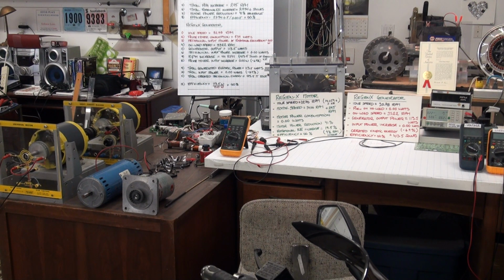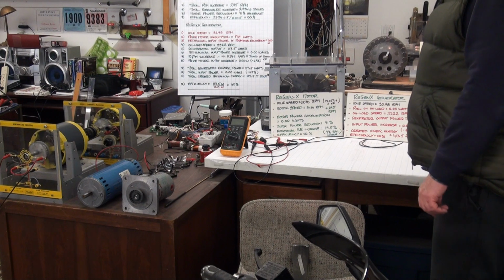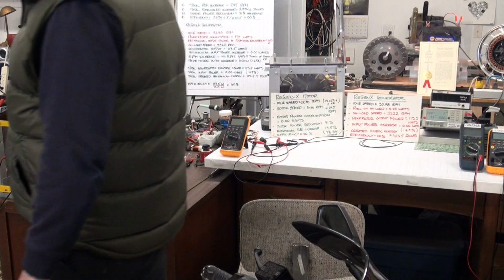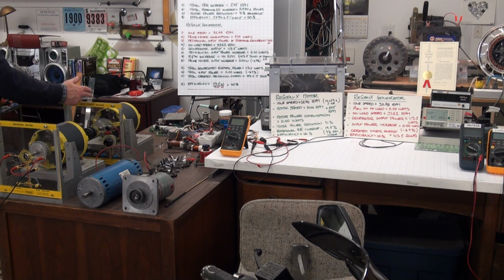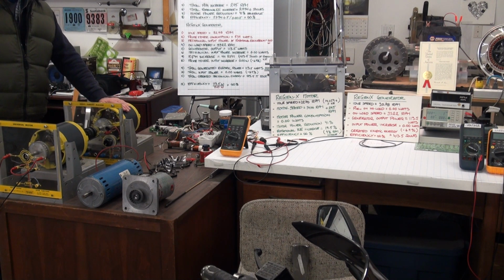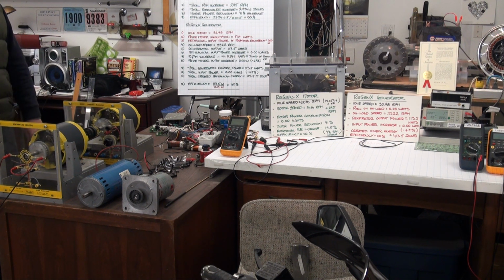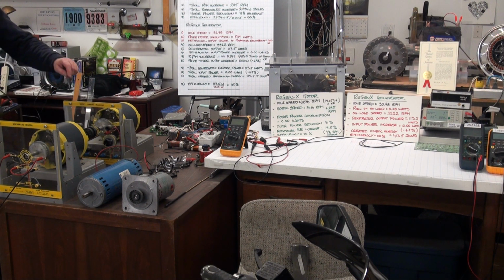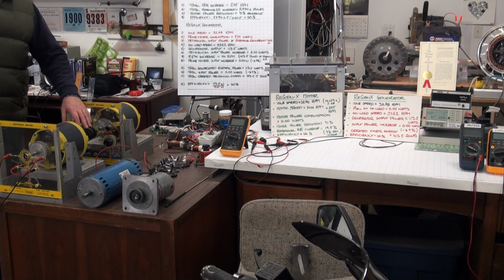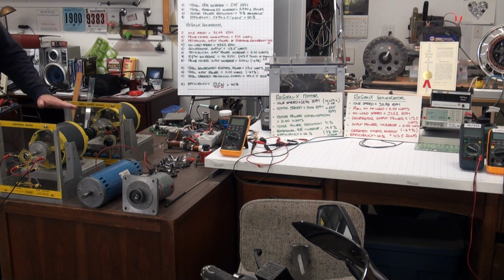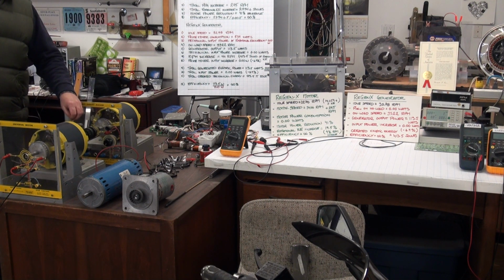And if I want to generate electric output power from my generator, I need to supply additional mechanical input power in the drive shaft above what is established at rotational equilibrium. Because at rotational equilibrium, or steady state speed, the power in the drive shaft is 0 watts.